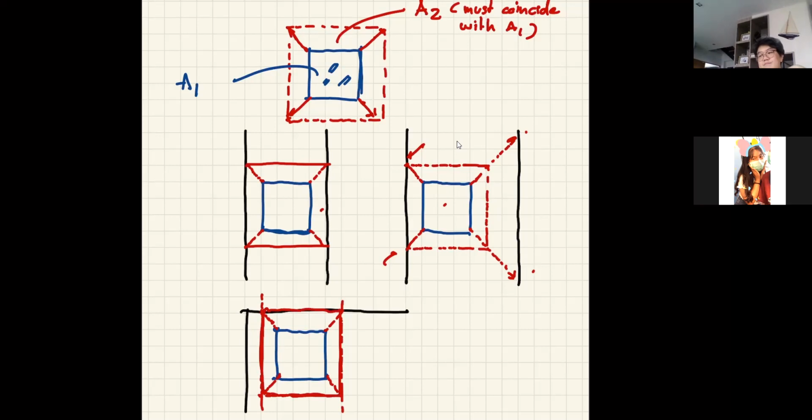Okay. Another case here. Let's say, what if I have a very large concrete and my steel plate is only this size. The question is, can my A2 go to infinity? Can I have my A2 go as far as I want? The answer is no. They have put a limitation on this.